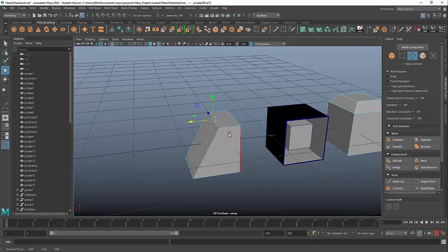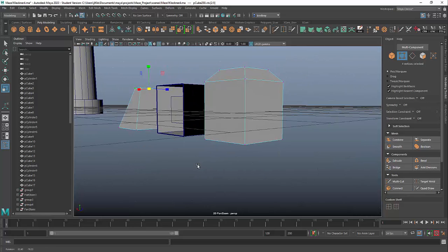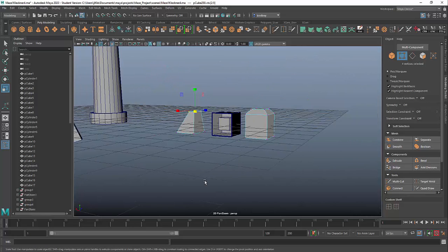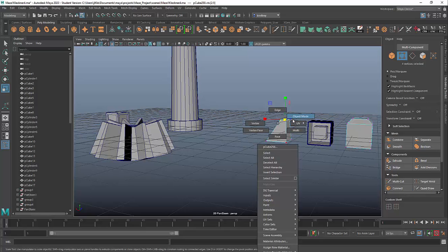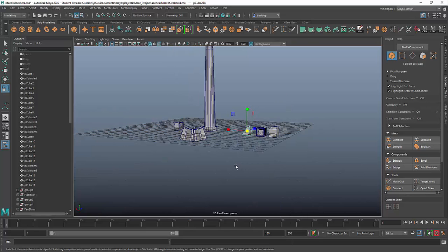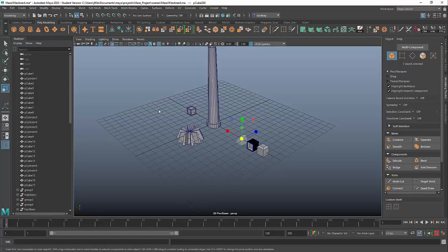If I want it to be tapered in uniformly though, I go to vertices and scale in using the scale tool and just grab that center cube, and that will taper it in like we did with the column up there. So again, you can try and do something very simple like this, but you can take a simple cube. Let me just grab all these real quick.